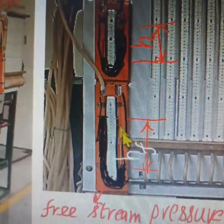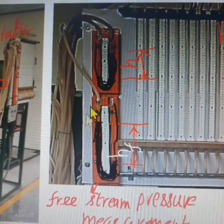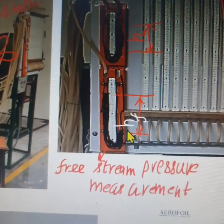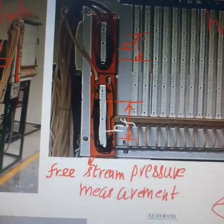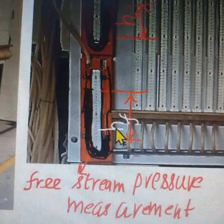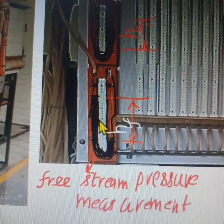This is the manometer used to record the free stream pressure. One end of the manometer is open to atmosphere, and the other end is taken to the test section. HF is the reading recorded on this manometer, which has water as the manometer fluid. HF is the water level difference on this manometer.